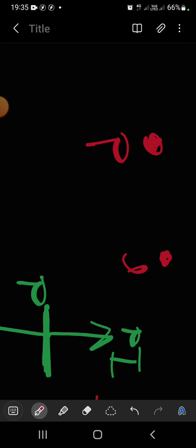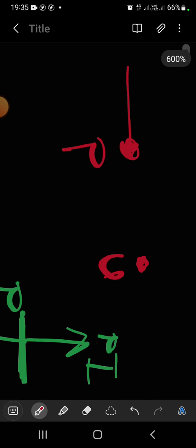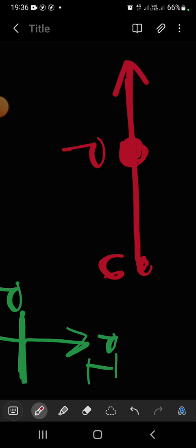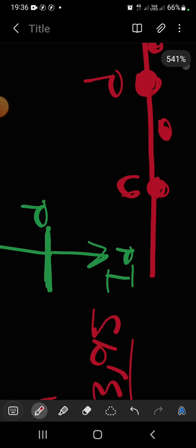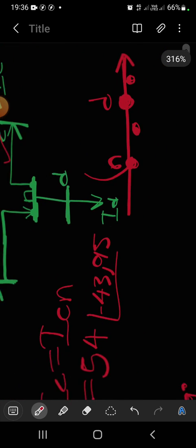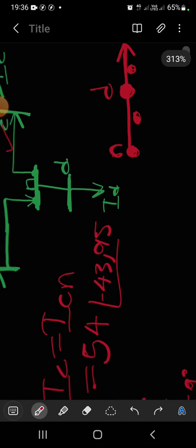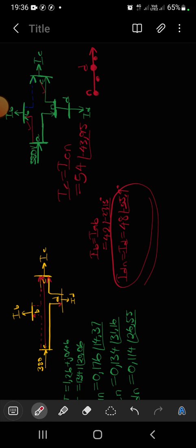I feel like I didn't explain it. You have point D there, and then you have point N there. We just know that the current out of that point is that 48. But then we have a wire from this point to this point. It's not going anywhere, it's not splitting or changing directions, it's the same wire, right? So series connection, current here is equal to current there. Now we have a lot of wires coming into N: that's AN, then we have CN. I wanted to show you that our IDN is equal to current ID, right? I hope now you saw it.